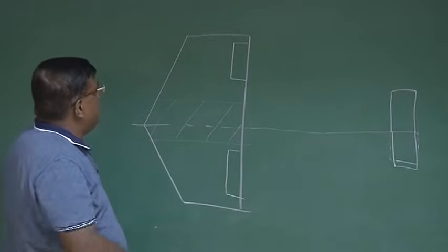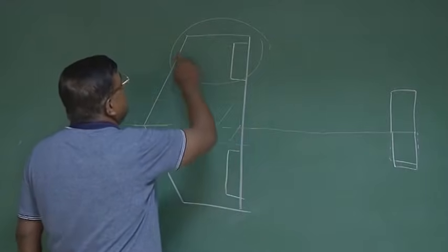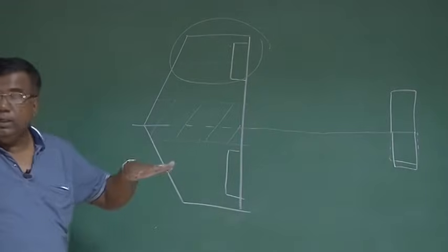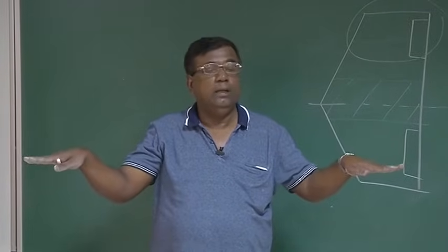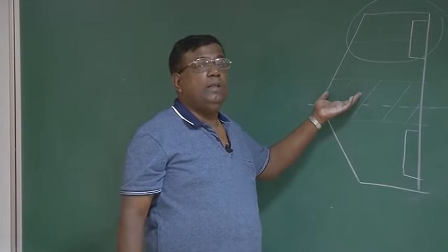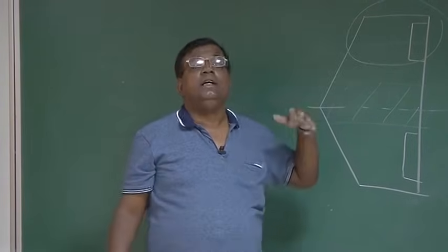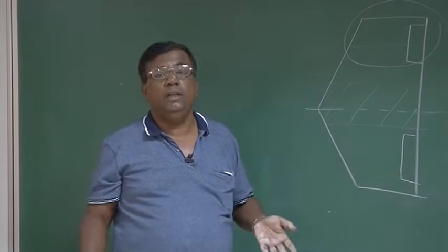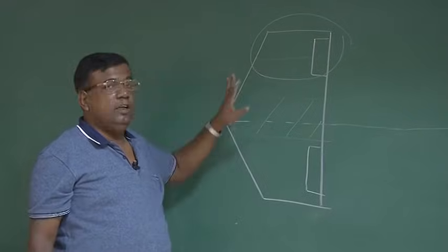So one way is we give a geometric twist at this portion, that is in the tip, you put a slight negative angle, so that even if here it is around 12-13 degrees, which is closer to a stall, the area here is seeing less than 12 or 13 by 2 degrees. So that this will not stall, but this will stall. So now we can recover.